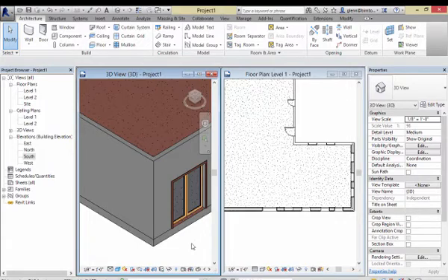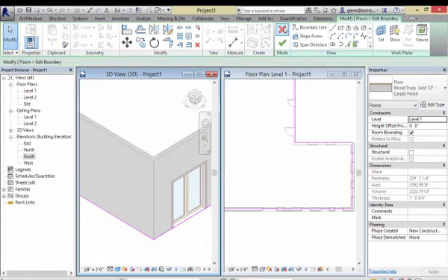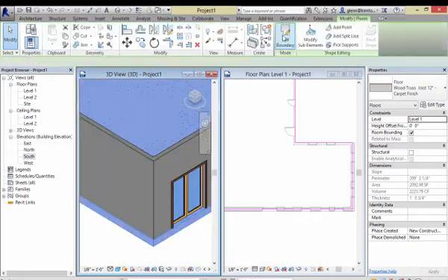Oh, so did you have the boundary drawn all the way around? Okay. Do you have a little green checkbox up in the Modify Floors tab? The check mark. Okay, click on that and see what happens. So the question is, once you've drawn the boundary and edited it, how do you actually complete it? How do you actually make it generate the geometry? And it's typically the green check mark.